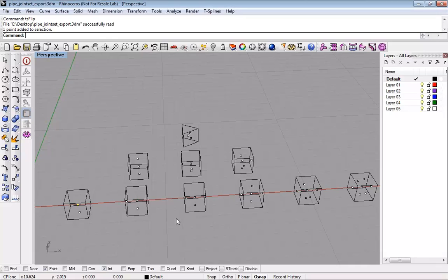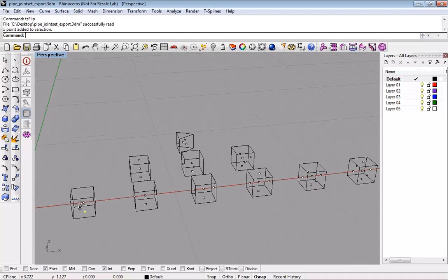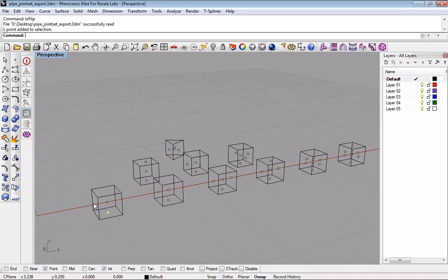And then, let's see, the last thing that I wanted to say about this is that there are a couple of restrictions. One is that these meshes aren't general T-Splines at the moment, although that will probably change. They're just subdivision surface meshes. So any Rhino mesh will do. It won't pick up on T-junctions, and it won't handle the knots if you have them on your T-mesh.